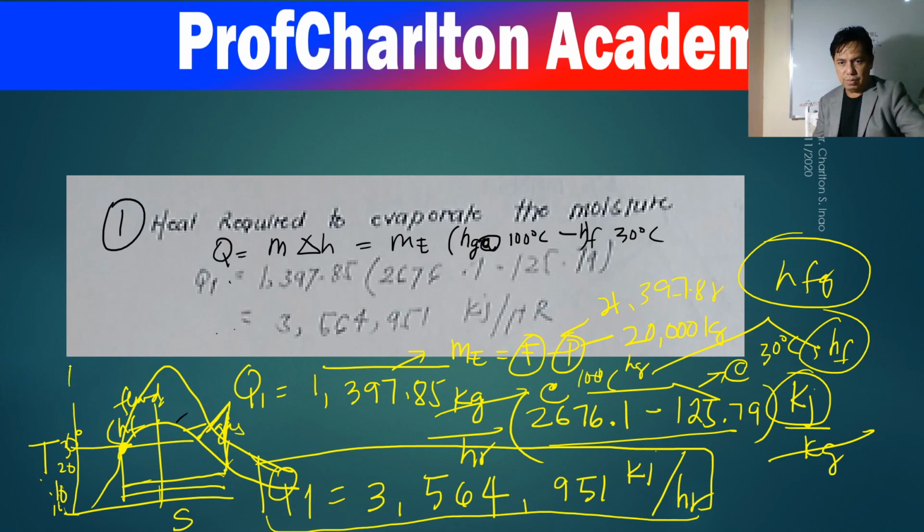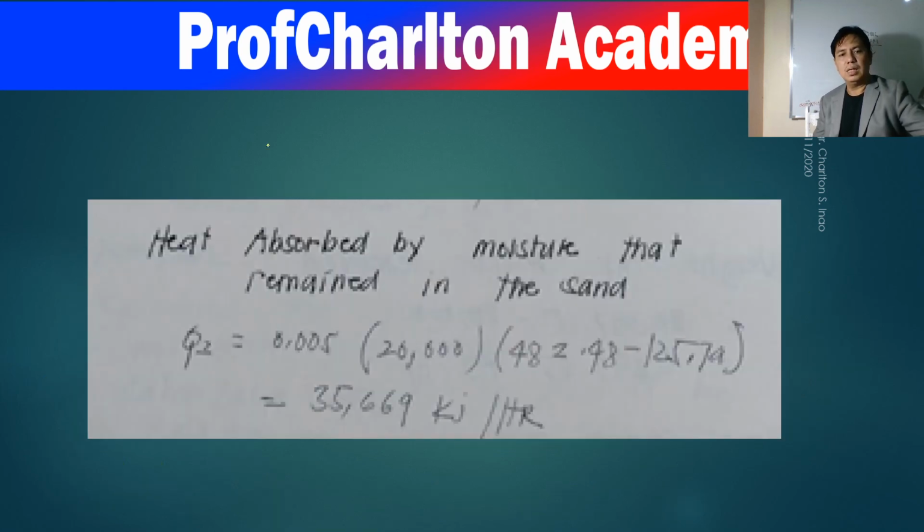100. Yeah? So if you continue this, if it's 100 degrees centigrade, you can project here, right? So 100 degree centigrade, because saturated gas, Hg. This one is HF. Yeah. So you can get the enthalpy, which is this, Hg and HF, right? Okay. So I think it's clear.